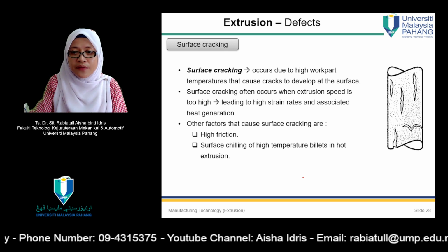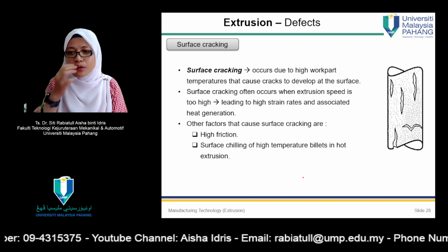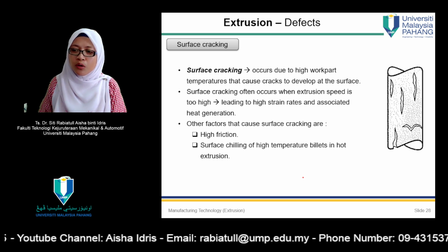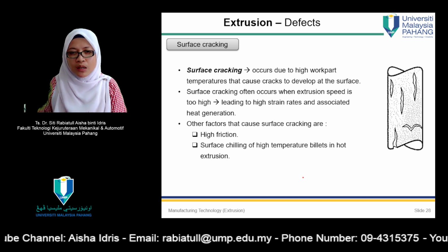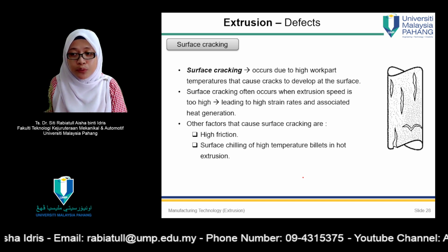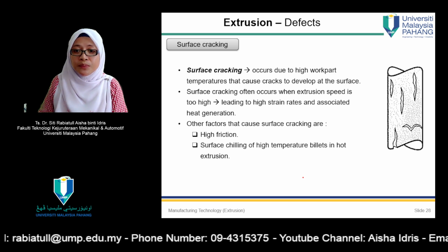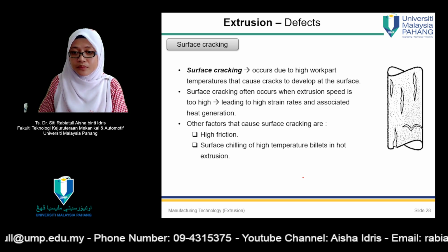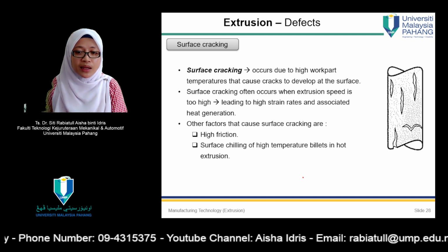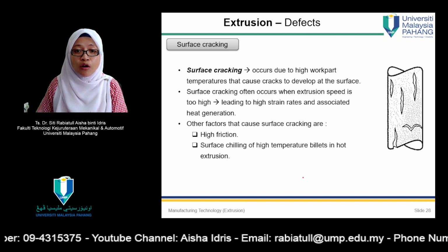And then surface defects. This commonly occurs after high temperature work or warm work. Warm work seldom occurs, but during hot working this might occur if we don't control the speed of the process. Other factors that cause surface cracking are high friction, surface chilling, or high temperature billets in hot extrusion.